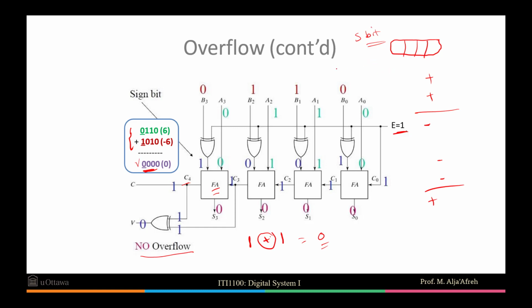So overflow is a big issue when it comes to computers and can be detected by XORing the carry going to and from the sign bit.